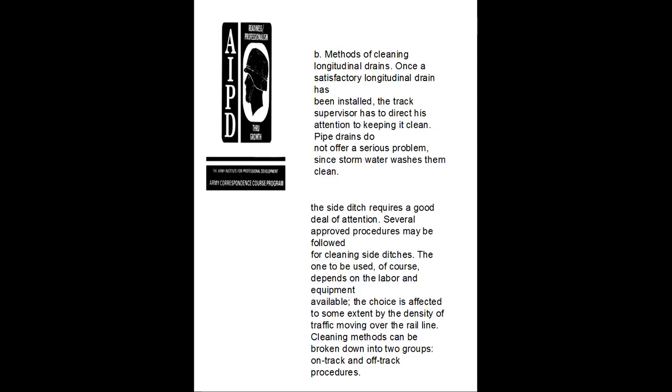The method of cleaning longitudinal drains: once a satisfactory longitudinal drain has been installed, the track supervisor has to direct his attention to keeping it clean. Pipe drains do not offer serious problems, since the storm water washes them clean.